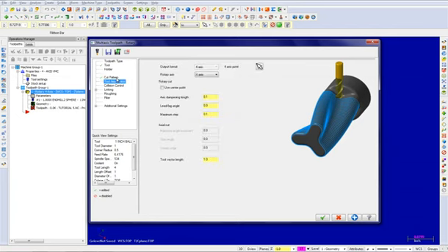Select Tool Axis Control. The Tool Axis Control settings determine the tool's orientation in relation to the geometry being cut. Rotary axis determines which axis is to act as the rotary axis in Mastercam. In this case, use the x-axis. Use Center Point allows you to generate tool vectors that terminate at the selected point. Deselect it to generate tool vectors that are normal to the surface.